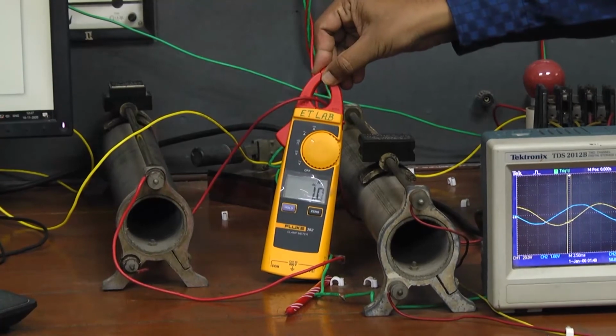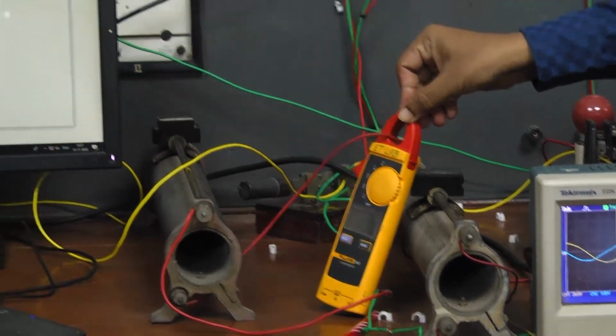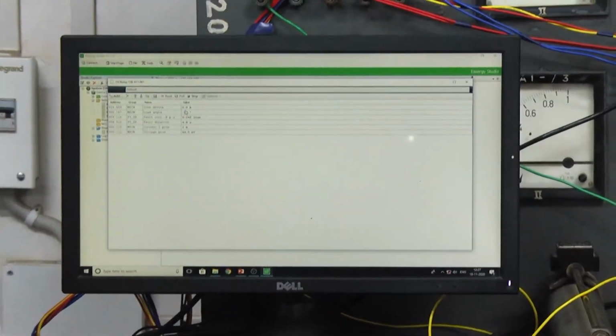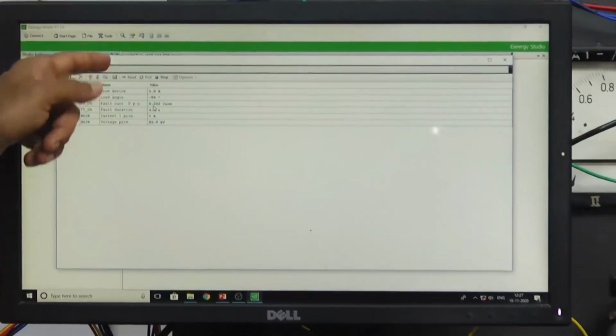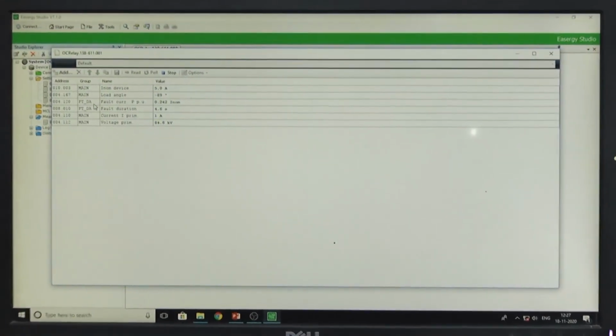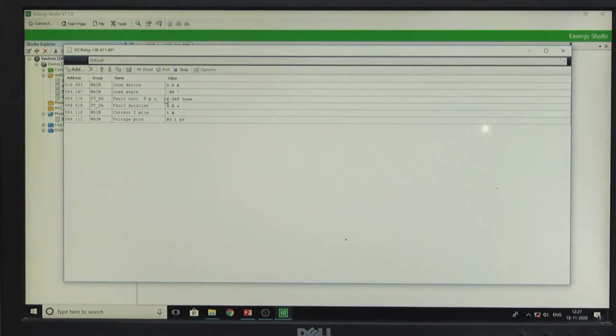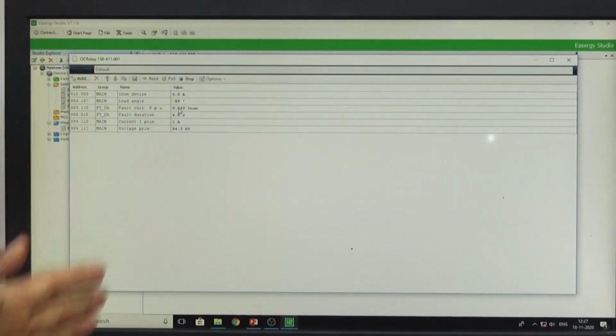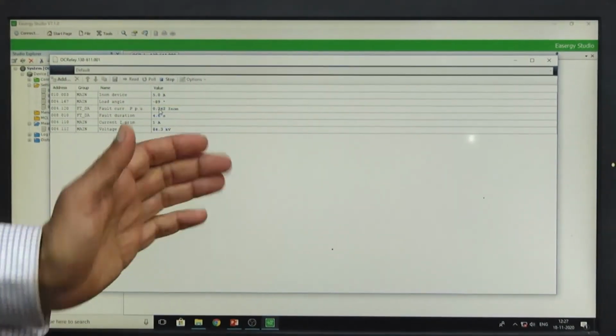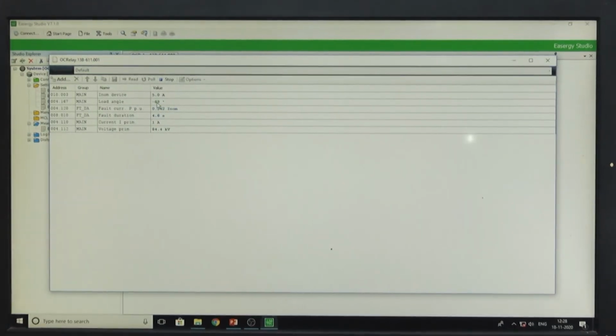Therefore, because this current is below the corresponding 1.5 ampere as per the fault current level, it is not operating at this moment from the overcurrent principle perspective. In addition, because our gamma is set to minus 45 degrees, the angle is beyond that also. So, the directional relay is also not in the operating mode in this particular case.